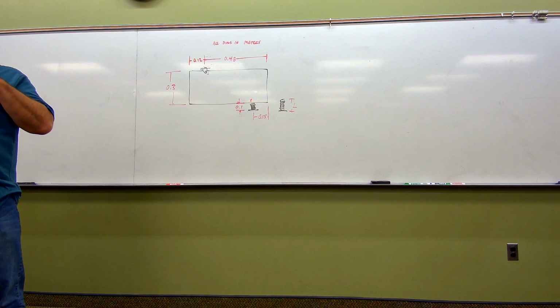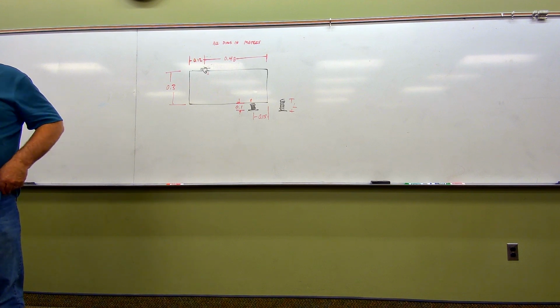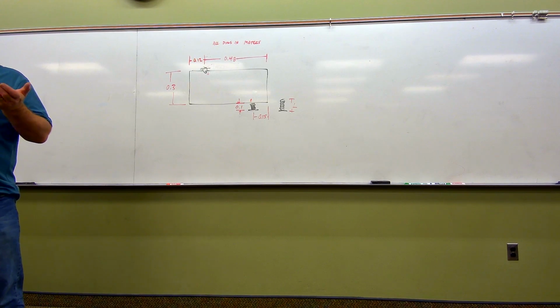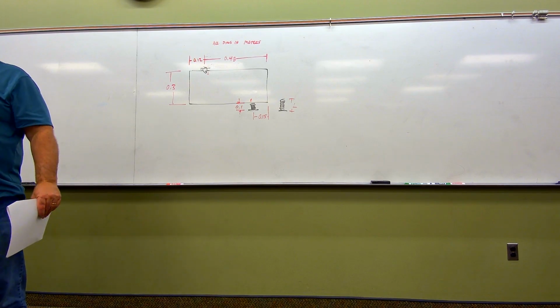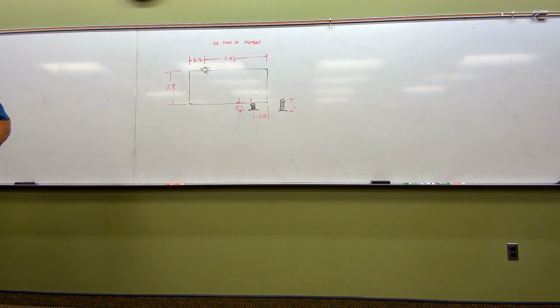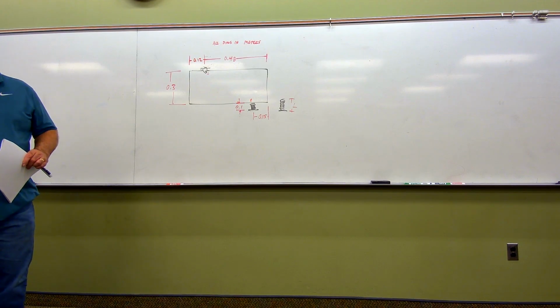The very first 2 or 3 words of the narrative go like this: the 20 kilogram uniform rectangular plate. If I'm you, I stop right there. I just saw kilogram. I couldn't care less about what the rest of this reads, but I saw kilogram, and I know that I have to convert that to its equivalent in terms of weight.